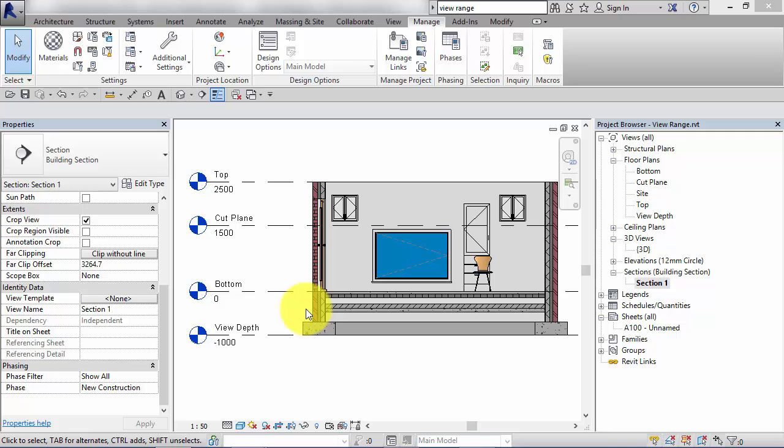Likewise with structural floors, they would be displayed in projection. And stairs and ramps, they have a tolerance of about 1.2 meters. So if you've got stairs that project down below the bottom of the primary range, or a ramp, then for the first approximately 1.2 meters, that stair or that ramp would be drawn in its projected line style. Then below 1.2, if there's any more of the stair or ramp left, then it switches to the beyond line style. So just watch out for that one.